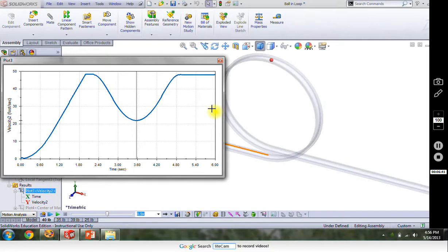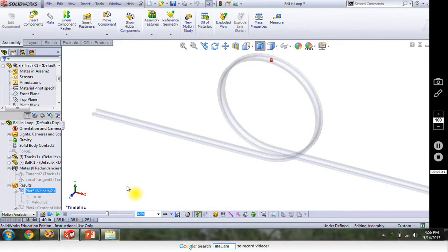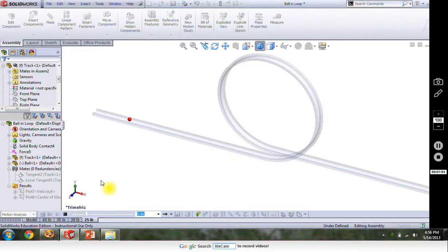If we drop the force much at all, then our velocity is going to drop below that necessary to keep the ball engaged with the loop. And in fact, let's go down to a very low force here of 25 pounds. So drop from 40 down to 25 pounds. And you can see in this case, the force is not enough to get the velocity high enough to even be able to make it halfway up the loop. If we increase that up to 35 pounds, we'll see how accurate our calculations are, because this should be just not quite enough to get there, and we can see, yeah, that is the case. Don't quite make it there.